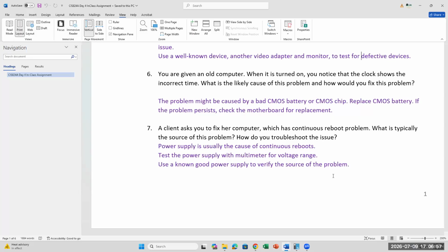Or you can buy the compressed canned air. But when you spray the compressed canned air, read the instructions. I know it's easy to skip reading the instructions on the canned air, right? Attach the nozzle, and they tell you how to angle it, because when you spray excessively, the can gets really cold, right? You're going to notice that there's a little powder residue from the gas they put inside the canned air. So be mindful, and when you spray it, keep it at a distance, because that little particle gets onto your motherboard, and when you turn it on, it can also be damaging.